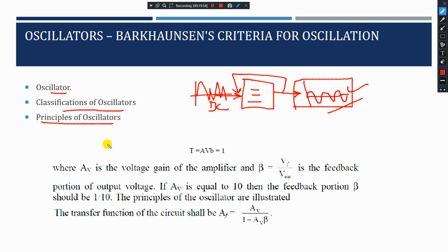output signal is fed back to the input without any phase change. I'll come back to that. What is that? You may not understand if I say that. See, there is an output. What it says is there is a positive feedback. I'm giving a positive feedback to this. A portion of your output will become an input to your oscillator. So this is without phase change. That's how the principles of oscillator work.